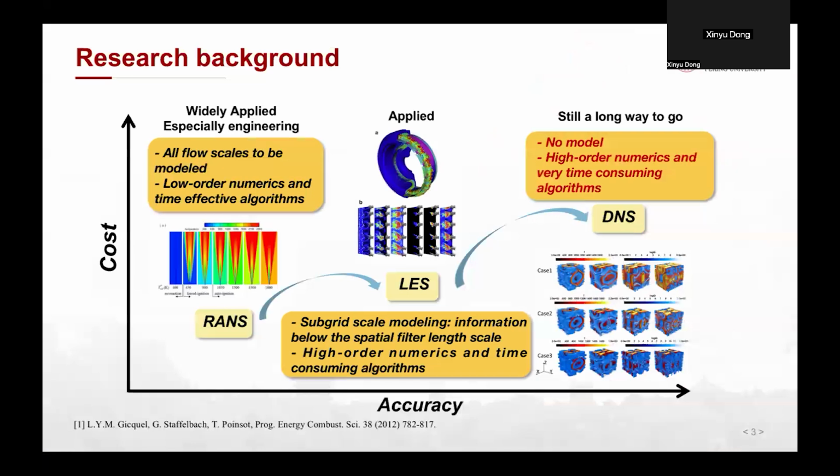In combustion simulation, there has long been a trade-off between accuracy and efficiency. Currently, in the engineering field, RANS and LES methods have been widely applied. However, these models, which contain many physical assumptions, are increasingly unable to meet the requirements for detailed numerical simulations under extreme conditions. While the DNS method, direct numerical simulation, is a first-principles model for combustion, it is still considered a computationally unaffordable simulation method.